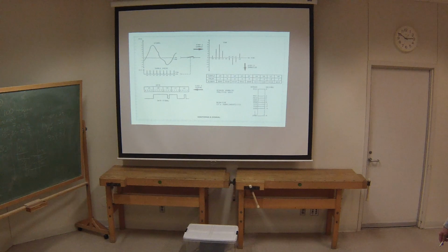Now, there are some basic steps in converting an analog signal to digital. The first one is represented here. This is called sample and hold, and if you want to draw a little capacitor to ground from here, that would probably be good, because what we're going to do is feed this analog signal in, and this switch is going to be toggled closed by these sample pulses here.